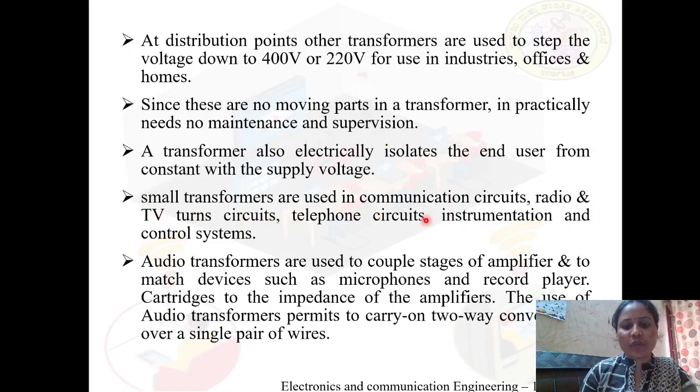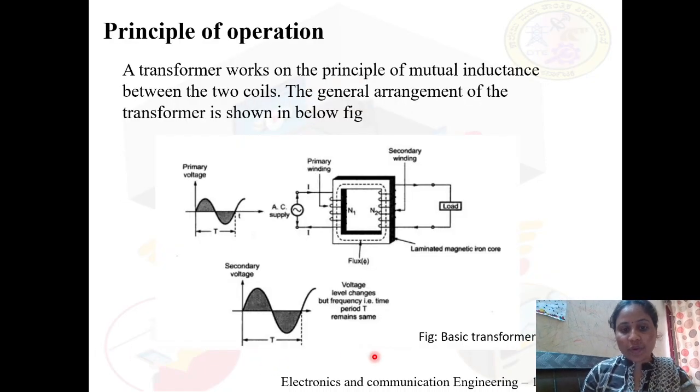Small transformers can be used in communication circuits, in radio and TV tuner circuits, telephone circuits, instrumentation, and also in control systems. We make use of audio transformers for coupling the amplifier stages, that is, as matching devices for microphones and record players. Therefore, the audio transformer helps to carry on a two-way conversation over a single pair of wires.